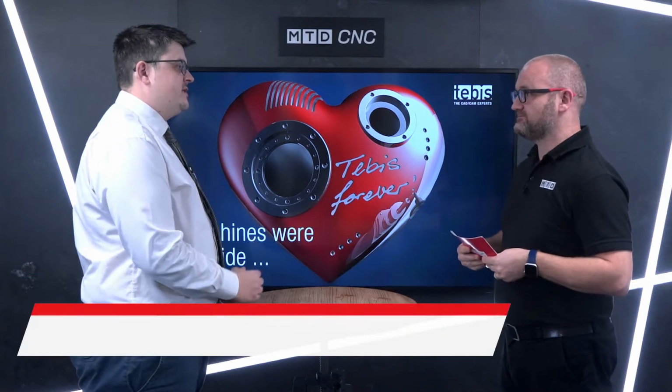For Tebis, features is basically a way of recognising CAD data within the model. Once we've recognised this CAD data and assigned some basic parameters to it, we can then add predefined machining operations to it and use this to drive our programming process.